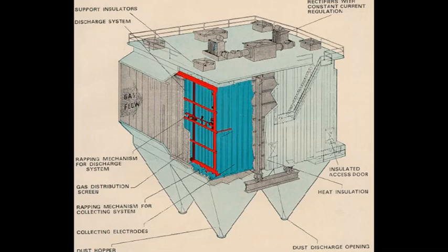We have many types of arrangement, mostly mechanical dust collectors in some of the plants, and in all the plants we find electrostatic precipitators, which is equipment that charges the ash particles, fly ash particles, and gets them collected on collecting plates in the electrostatic precipitator, and that is again transported to the ash handling plant and disposed in some ash dikes.